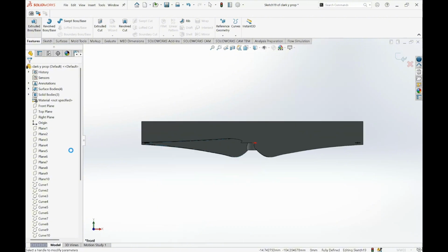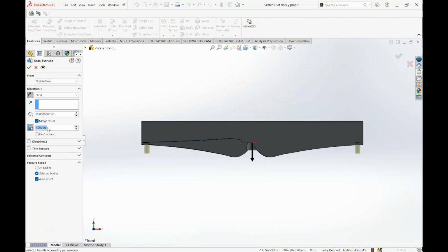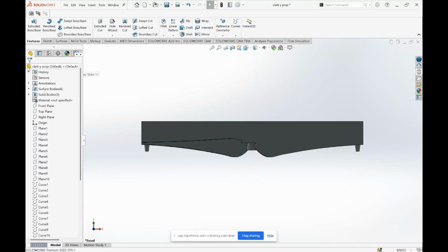As you can see, to form the guiding pins, we just have to use the extrude tool with a slight draft angle so that we can ensure that the mold will have a proper alignment and a smooth release during the closing or the separation of the mold.